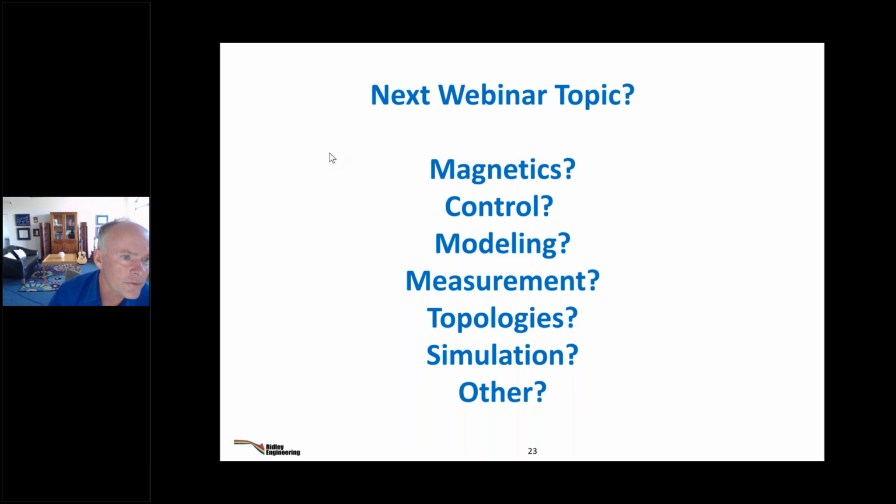Can you do constant frequency LLC? People do constant frequency LLC, but they don't regulate at the same time. Can you modulate inductors? Yes, you can, but that becomes lossy. Best way to current share LLC? It's hard. It's hard when you do synchronous rectifier secondary and then you put the two in parallel. You can get situations where one LLC starts running backwards.